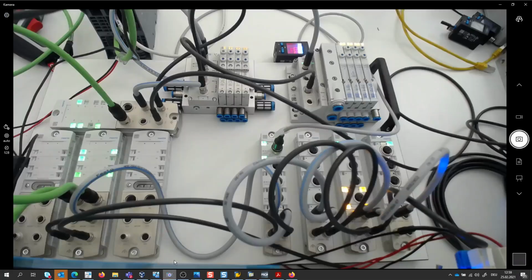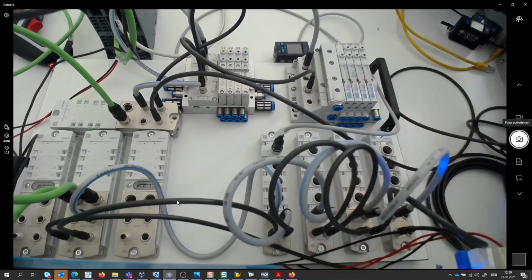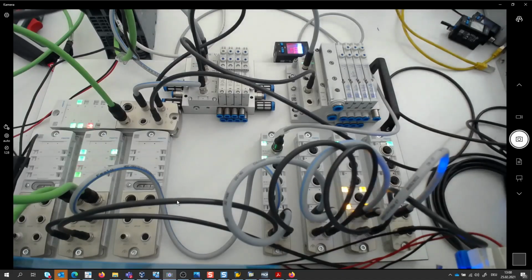You see now the options are activated, and if I'm now making again this power return, it takes around 2 till 5 seconds till my coils are switched on. This is much faster, but not fast enough in tool change applications in the automotive. There we have to achieve times between 500 milliseconds till, I would say, 1 second maximum.